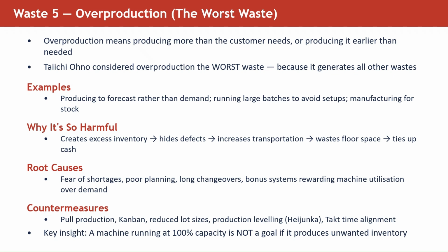Why? Because overproduction is the master waste. It generates all the other wastes. When you produce more than the customer needs or earlier than they need it, you create inventory. That inventory requires transportation to storage. It occupies floor space, causes motion waste, hides defects, and consumes machine capacity that could have produced something valuable. Overproduction looks productive. Machines are running, operators are busy, output numbers are high, but the product being made is not needed yet, or possibly ever. It is a waste wearing the costume of productivity.